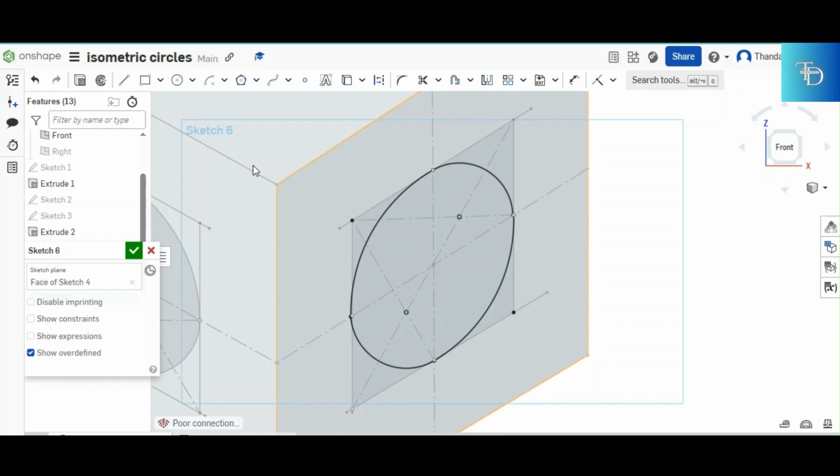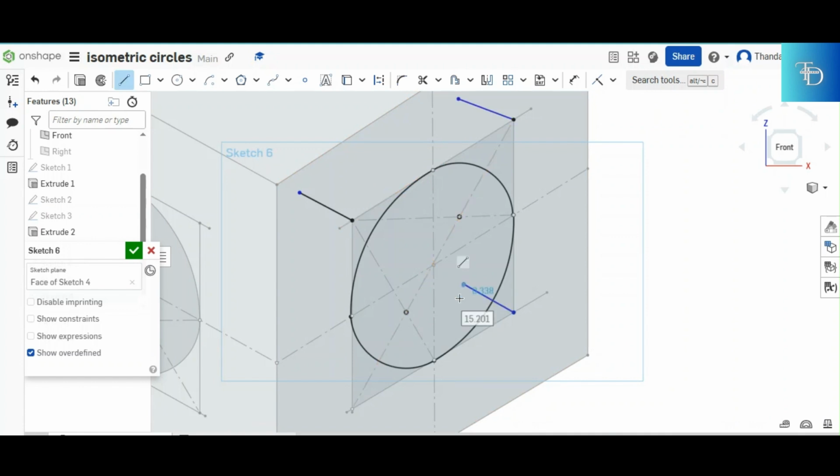So what you do, you have to enlarge all the four corners of this square right there. The very same square that you used to create the first circle. So by that, you pull up your 30-degree ruler, you place it right there at the corner, you enlarge by 15. You do the same thing for the other corner. You move over to the third, you enlarge by 15, and then you go over to the final point. You pull it by 15 also.